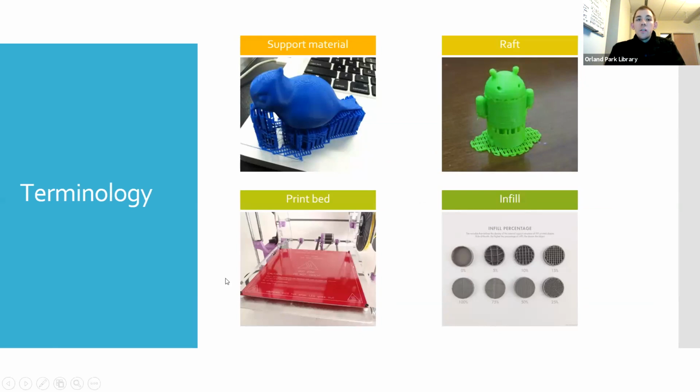And you can see right here, the support material has a picture of it, that there's support material to elevate this portion right here, and it elevates it from the bottom. It's like a very thin material, so then this gets raised. And then there's the raft, which, like I said before, is a base, so that this thing doesn't come out lopsided or off center right here.